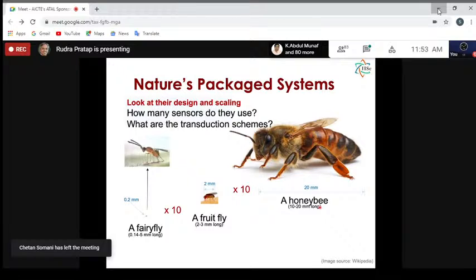So I have a certain transparent region in the mask like this. If I do UV exposure, then the UV will only go through where the mask has transparency. There the UV goes to the photoresist and reacts with it. Once it reacts, the bonds break there, and if I put it in a developer, then that part of the photoresist will be gone, right? So I have removed photoresist only from a selected area. So photoresist is gone from there.